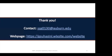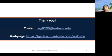Well, I'm brave enough. This is Chris Crumley. Some of your investigations, can they be done non-destructively to understand what may already be through the supply chain, and what has been produced? Oh, absolutely. The micro CT work that I was depicting is essentially non-destructive testing that can be done to understand the microstructure in relation to the process parameters. We have also done infrared thermography to look at defects that exist in components. And of course, ultrasonics can also be used.